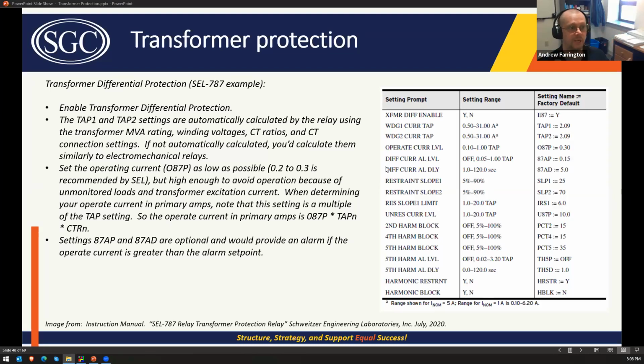It's that the physical phase shift isn't what you thought it was and programmed the relay to look at, and what they tested to, because they tested what you told them to set it to. So, final in-service check, try and get those. And like I said, bus differential relays too, more importantly than these transformer differential relays, it happens all the time.